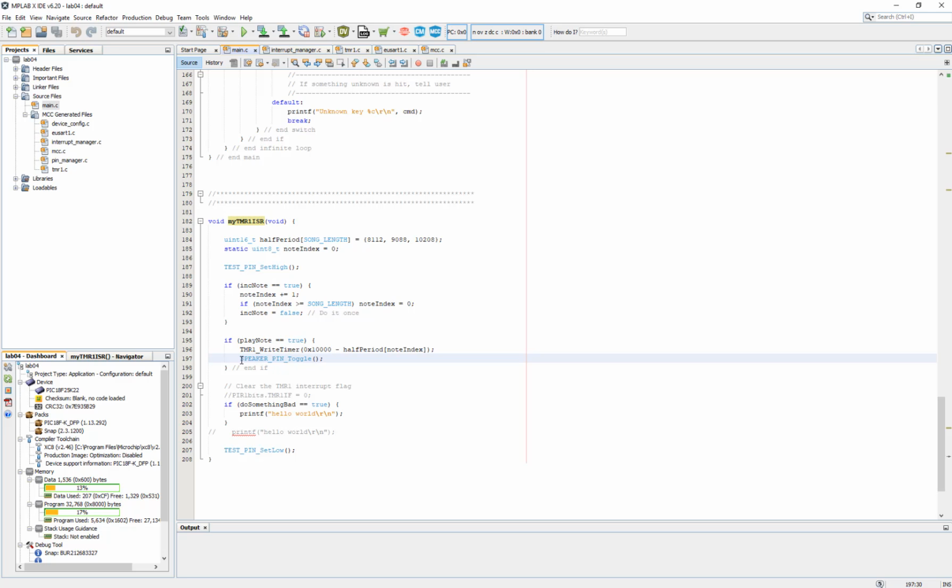It's 2 to the 16th counts, right? And it's counting at 16 megahertz. We used these two numbers to find out. It runs through all the counts and turns on the flag. The whole process takes 4.1 something milliseconds, so it takes 4.1 milliseconds to overflow.